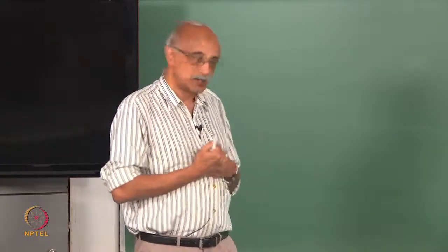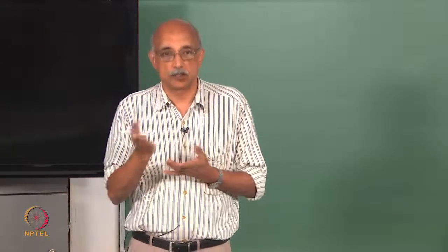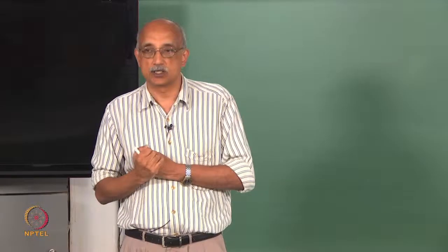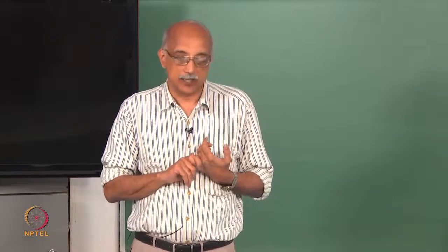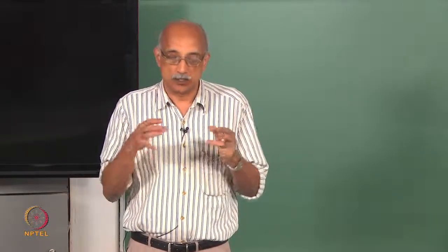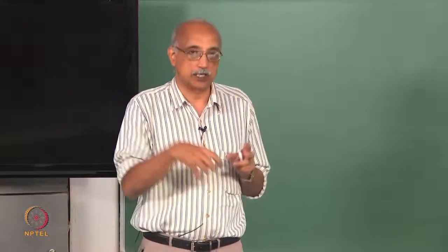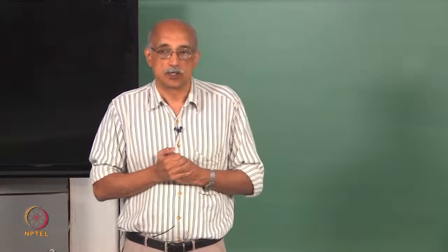However, what is going to happen in reality? Are you going to be able to control it this well? No, because of some of the problems I was talking about earlier. If you have non-spherical particles, there is a mechanism called blinding where so much material accumulates in one place that no more particles can pass through. So, periodically the screens have to be cleaned and so on.